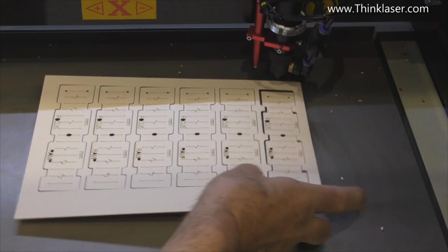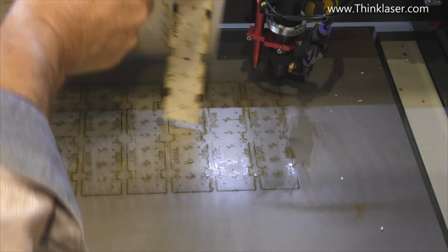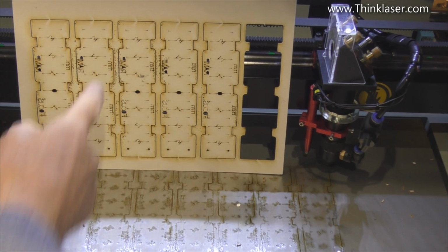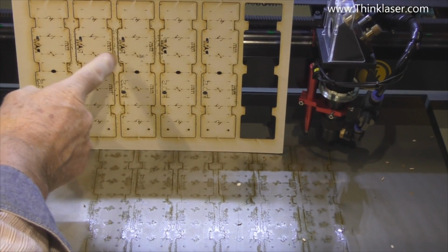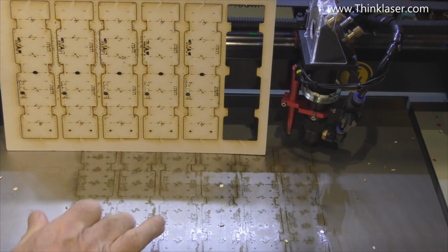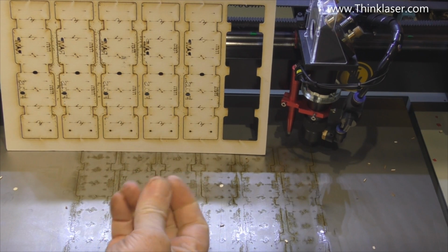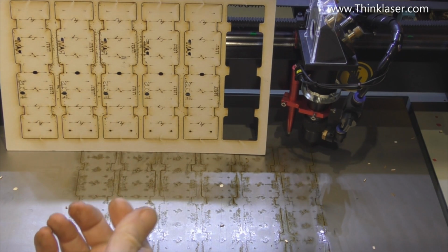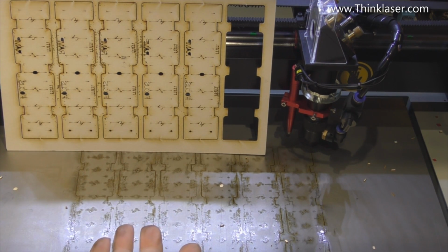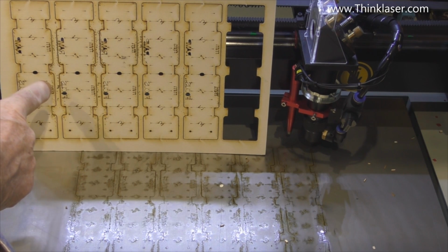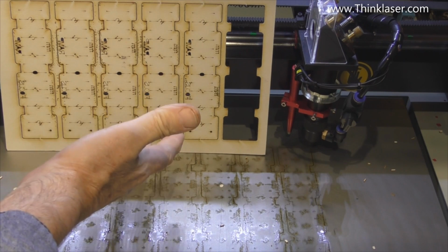But that's not the only problem that we've got with this approach. We have two problems. Number one, we've blown out a huge amount of tar. In other words, the cellulose, when it's cut, produces this tarry residue because it's a wood, there's a resin in there, and it's all sticky on the table. Now that's a major disadvantage in one way, but hey, if it wasn't on the table, it would be in the filter. That's what's not on the back of the product. So this really is not a very satisfactory approach for cutting things.